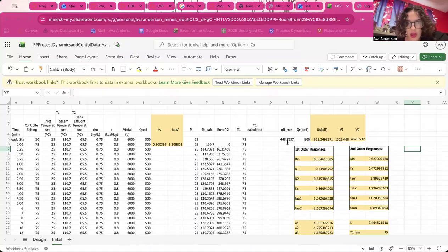And we're applying a step change in the steam valve position. It's applied during the test run at a reduced flow rate of 105 liters per minute, and the resulting temperature responses were used to identify the system parameters. So that's just the first part of my hand calculations.